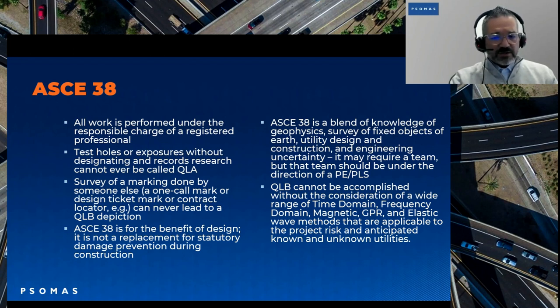ASCE 38 is for the benefit of design. It is not the replacement of damage prevention during construction. Understand that ASCE 38 is for before construction. Understand that this is to assist the design professional in putting together what they're doing.